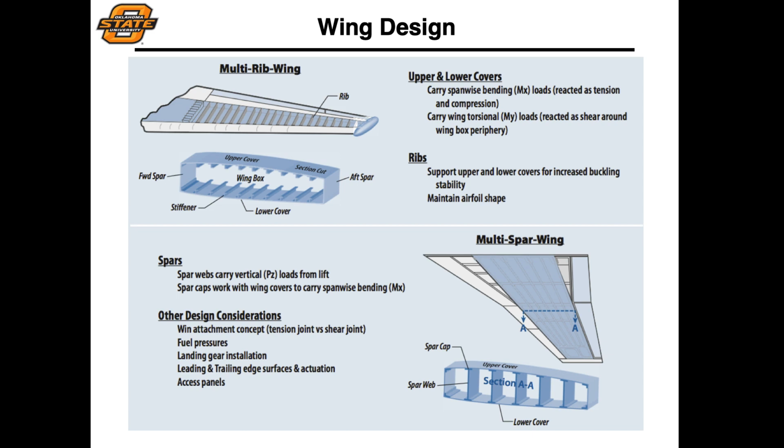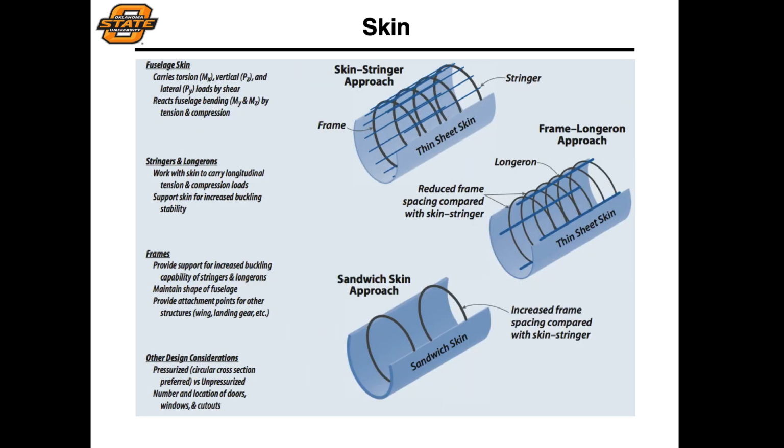Primarily, that depends upon how you utilize the ability to minimize your weight while maximizing your cross-sectional moment of inertia. So you really want that capability to transfer those loads from the cross-section along the length to the fuselage portion of your aircraft. Likewise with the skin, you can have lots of different ways that you can design the load-bearing capabilities of your skin.